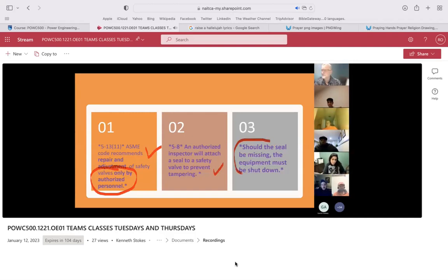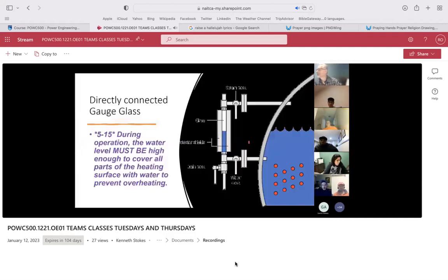And if you do tour around your boiler and see there's no seal on the safety, you better be talking to management and thinking about shutting down. If an inspector were to arrive on your site and find no seal or a valid inspection tag on your safety, he'd be shutting you down for longer than you'd be down for if you initiated that on your own.